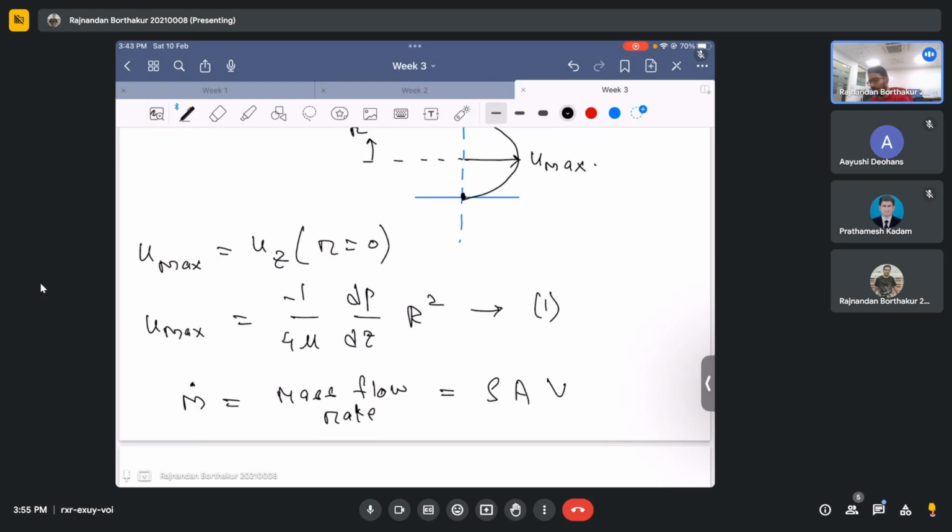The mass flow rate is rho times the volume flow rate, which is given to us. So this velocity will always have to be the average velocity and not the maximum velocity, because mass flow rate is a constant quantity. The mass flow rate should not vary along y. Since it is an average quantity, we need the velocity corresponding to it, which is the average velocity. All right.